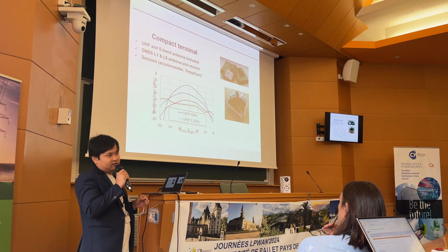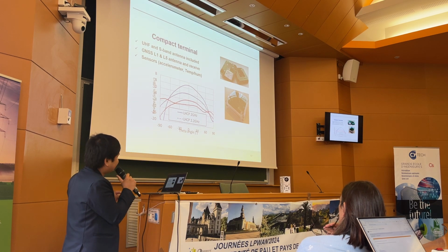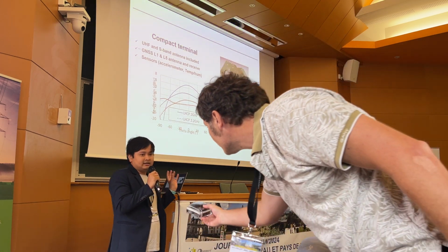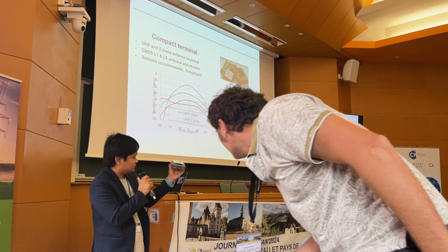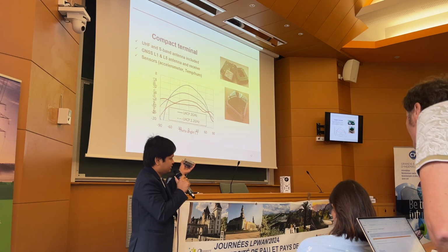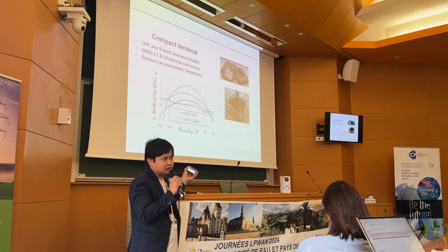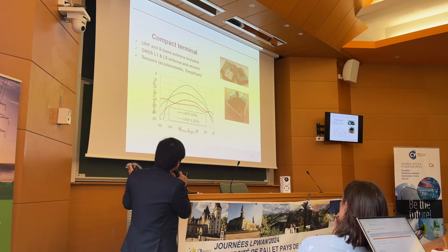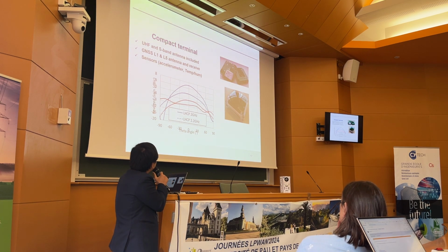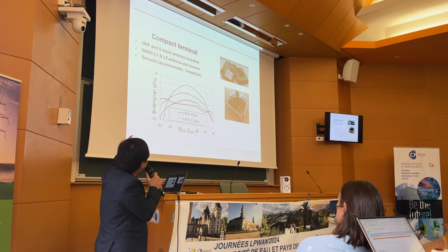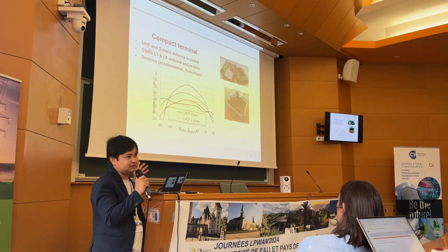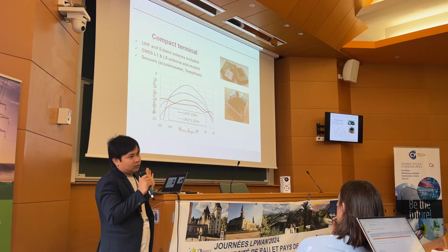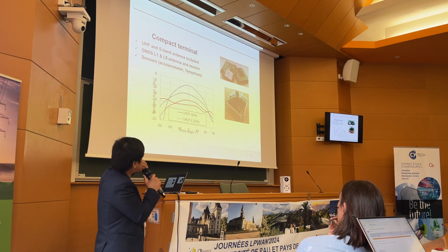So in terms of the terminal or antenna aspect of the device, this is the actual terminal. The dimension of the device is only 10 by 10 centimeters, and we integrate multiple antenna systems into it. We have the sub-GHz for the LoRa terrestrial network. We also have an S-band antenna for space or satellite communication.